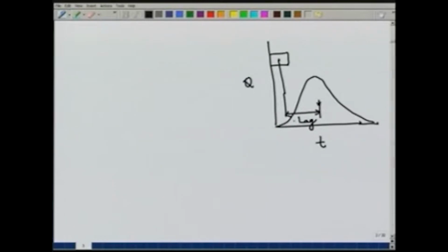The time lag between these two points is known as the basin lag, and typically a good duration for the unit hydrograph should be about 1/3 to 1/5 of the lag.